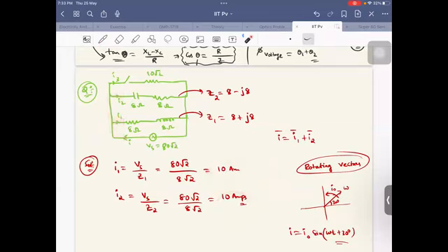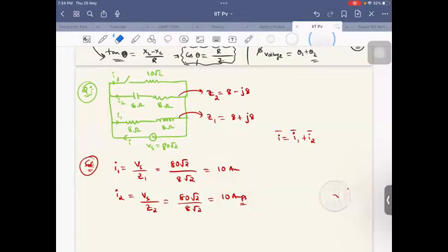So you need to either do the phasor sum, as I told, or else there's another way of solving it easily. What is the other way? Can you tell? The other way is, can I find Z equivalent or not? Because Z1 and Z2 I know. If I find Z equivalent, I can find the total I simply, because I know the source voltage. I want the source current only. So I will find Z equivalent.